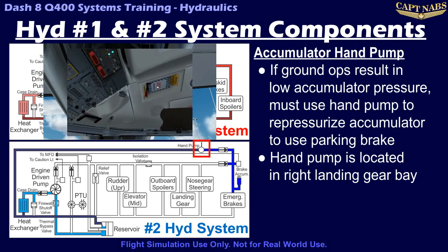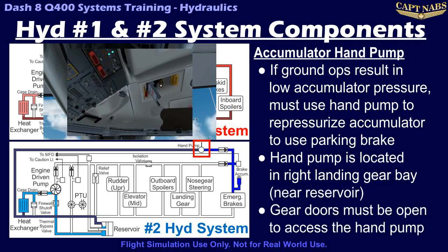Note that to access this hand pump, the landing gear doors must be opened. This can be accomplished by pulling the alternate landing gear extension handle in the flight deck.